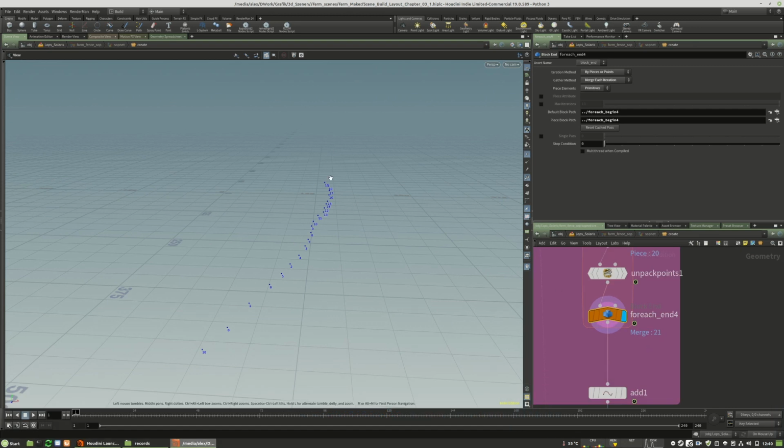So here I come back. I have played a lot with those values, and there's something that I want to show you. I have used the nudge tool in the layout and tried to move those points. And by doing that moving, the point numbers have changed totally. So we have totally different numbering now, and this could make a lot of problems by trying to create the fence object.